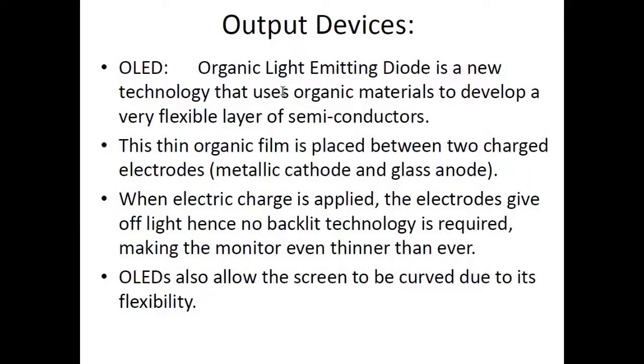Nowadays the technology has developed further, and we are able to develop a new technology that is known as OLED, or organic light emitting diode. It uses organic materials to develop a very flexible layer of semiconductors. This thin organic film is placed between 2 charged electrodes, metallic cathode and glass anode, and when electric charge is applied, the electrodes give off light. Hence, no backlit technology is required, making the monitor even thinner than ever.